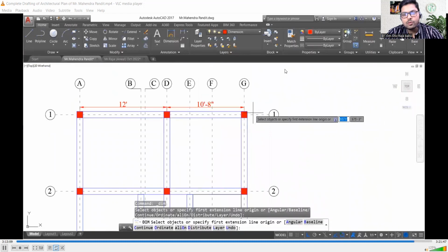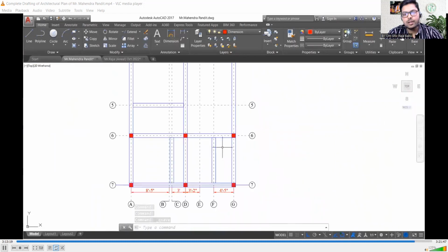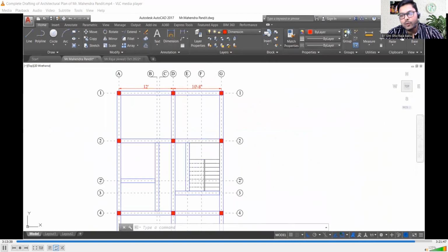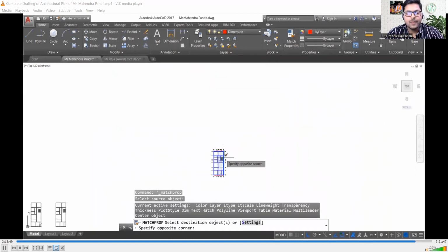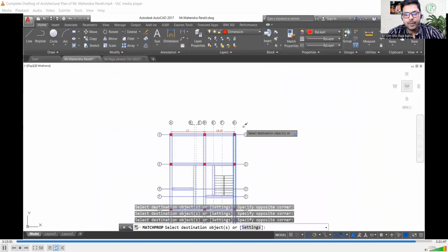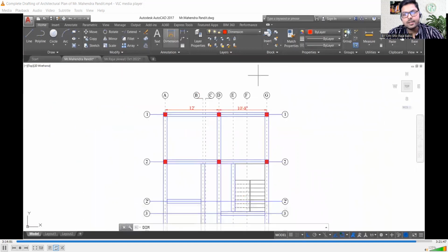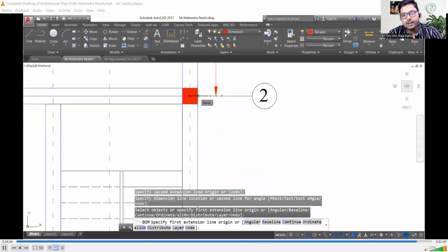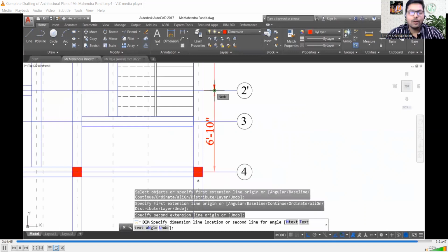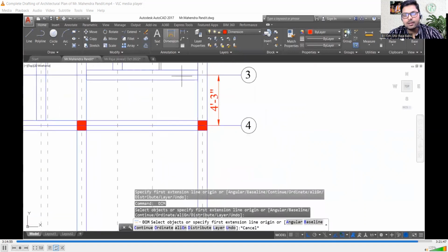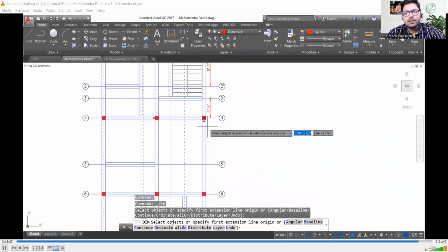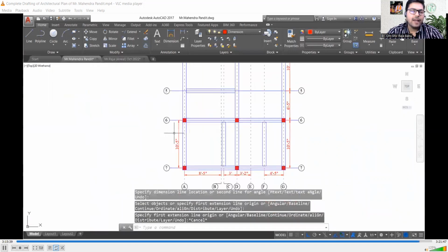Use the bold lines to mark the distances in case you are missing out any point, which is highly possible for the dashed lines. Make it bold and then mark the distances accurately. Then make it dashed again, because the center lines are meant to be dashed lines, not like the bold lines. However, even if you use another color, that is not an issue. But this is a general trend that we normally follow, that we mark it dashed so that it can be easily identified.